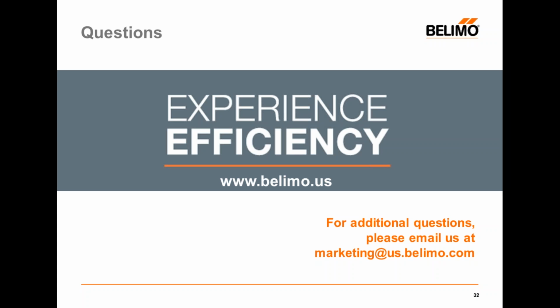Oh, that's a very good question. In some cases, building operators with larger buildings do prefer this, what we might call single seat control. So you can control and monitor both your HVAC and your fire alarm through one location. And this is especially relevant if you have a non-dedicated system where you're using your HVAC for smoke control as well. One thing to keep in mind, if in fact this is going to be done, the building automation system's front end has to be UL listed for smoke and fire alarm control.